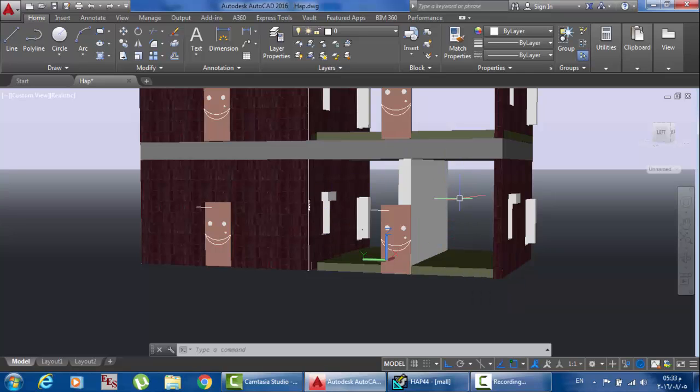If you treat this place as one zone and you have this wall, you do not have to take it as a partition, because the degrees will be the same, 24 Celsius, 24 Celsius, there is no heat transfer, so the area will be 0.